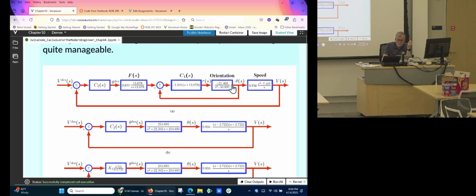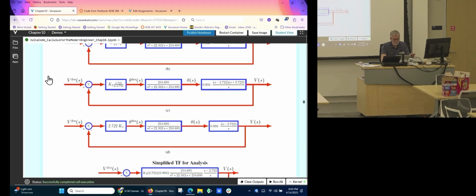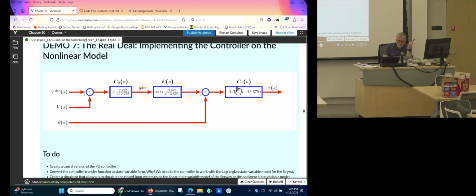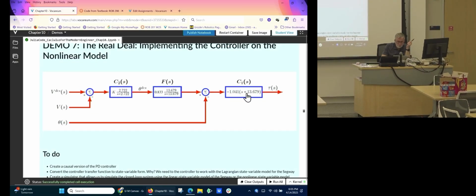So the measurement, torque, and stuff. This is the feedback diagram, but I want to remove the model because this is my controller. I set the desired velocity and I compute torque. To do that, I need to measure theta and v. So this is the PD controller. Okay, we are commanding theta desired as regulating the speed. So that's our C2 of S. Here's the precompensator.